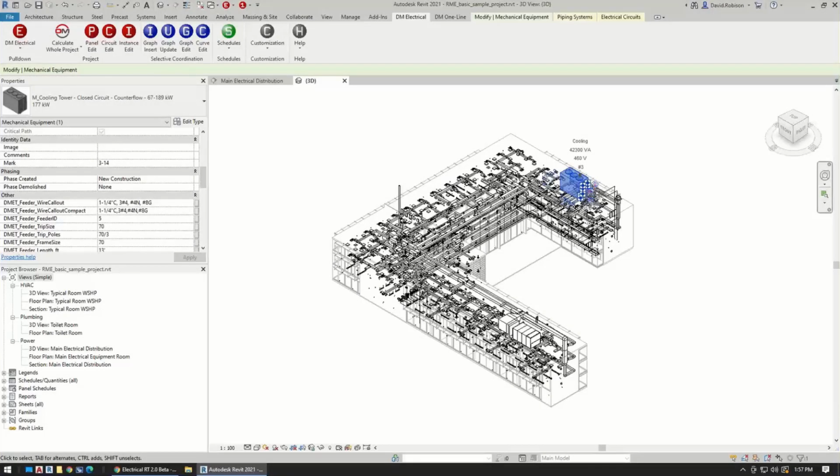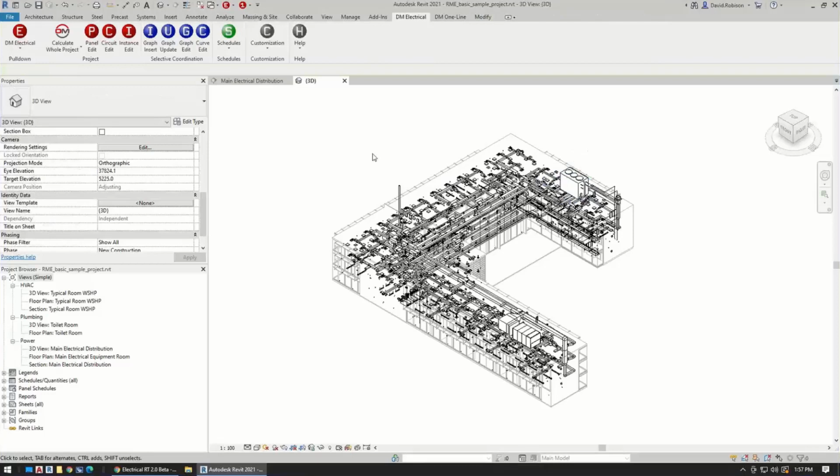That is it for wire sizing in Design Master Electrical. So the new features are the wire sizing options for a specific wire, where you can say it's going to be copper or aluminum, the wire ampacity, separate from the breaker ampacity, that we use for derating based on double neutral, and the ambient temperature. The rest of that's the new stuff. The rest of it hasn't changed, and that's how we do our wire sizing in our software.